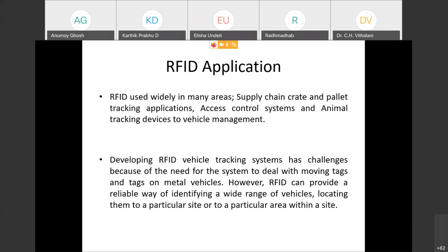So one of the design criteria of RFID tags is that I should give a metallic shield underneath the tag antenna, so that whenever the back radiated wave tries to reach the tag antenna, it will first encounter the metallic shield. Whenever it encounters the metallic shield, it will reflect the electromagnetic wave back to the car roof. So it will not let the reflected electromagnetic wave from the roof of the car hinder the radiated wave of the tag.